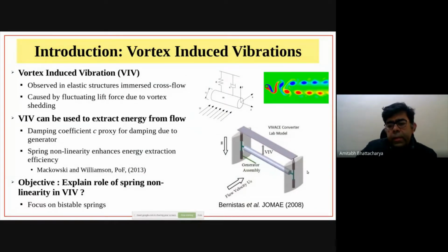And what they managed to do with that setup is actually control the damping as well as the spring constant through these servo motors, and that way they are actually able to really explore a very large range of parameters for the system, okay, without actually physically changing springs or physically changing the damping. And they managed to show, in fact, that you can actually generate up to about 20-30% of the energy from the fluid in this way, okay, which is a very large number, in fact.